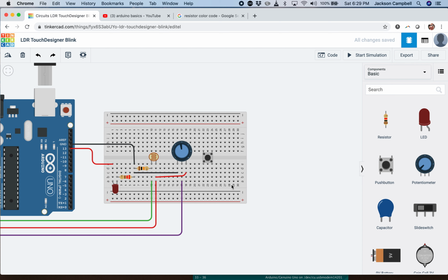And then when you push the button in, it provides an easier escape route to ground and doesn't go through its internal pull-up resistor, and so then it goes low. So instead of you pushing the button and it goes high, it's by default high, and when you push the button it goes low. And it's pretty easy to just change your programming to trigger when the pin goes low as opposed to when the pin goes high. And it's simpler to deal with. You have fewer components and fewer jumper cables.